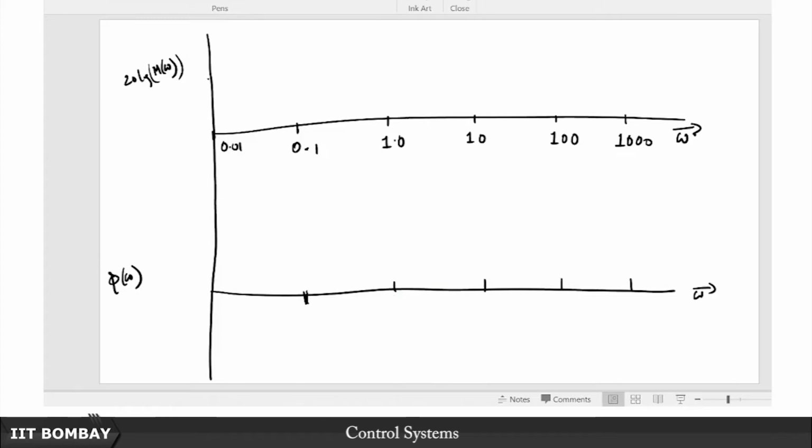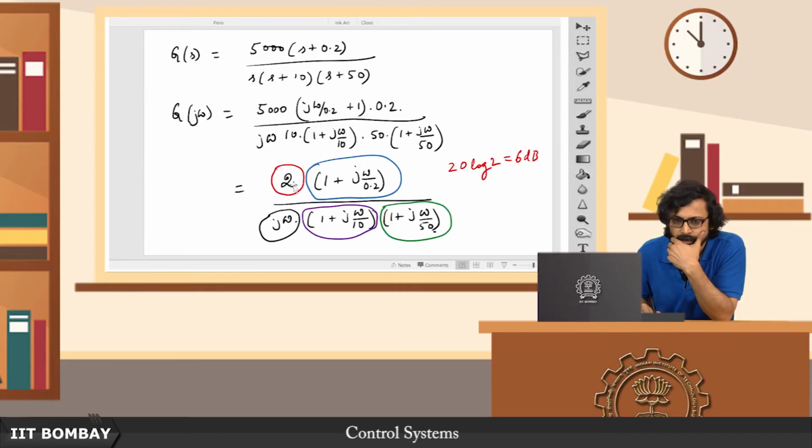So, let me have this 0 dB line here, this is 10, this is 20, or rather I can actually make it in scales of 20, because minimum is 20 dB per decade. So let me just make it 20, let me make it 40 here, let me make it minus 20 here, and make this minus 40 here. Because this is a linear scale, this is the first block, which is somewhere out here, it's a 6. Even if it doesn't look like a straight line, as you might have guessed by now that my drawing isn't very good, this is basically going to be the constant block.